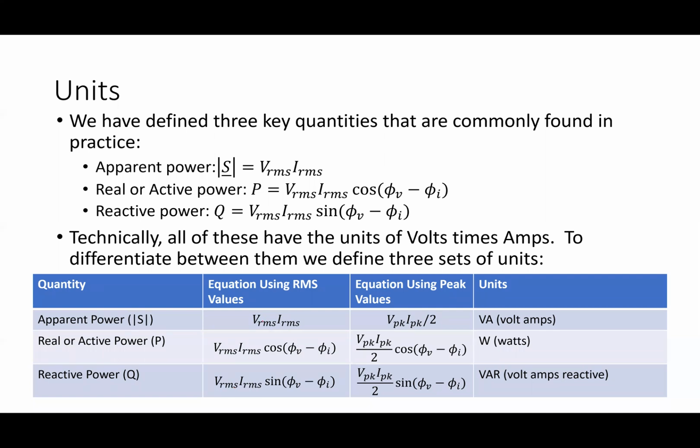If I'm talking apparent power, I say VA, or volts amps. If I say real power, we're talking watts. If I say reactive power, I'm talking VARs, volts amps reactive. Most commonly you will hear watts and VARs. You don't talk about apparent power as much.